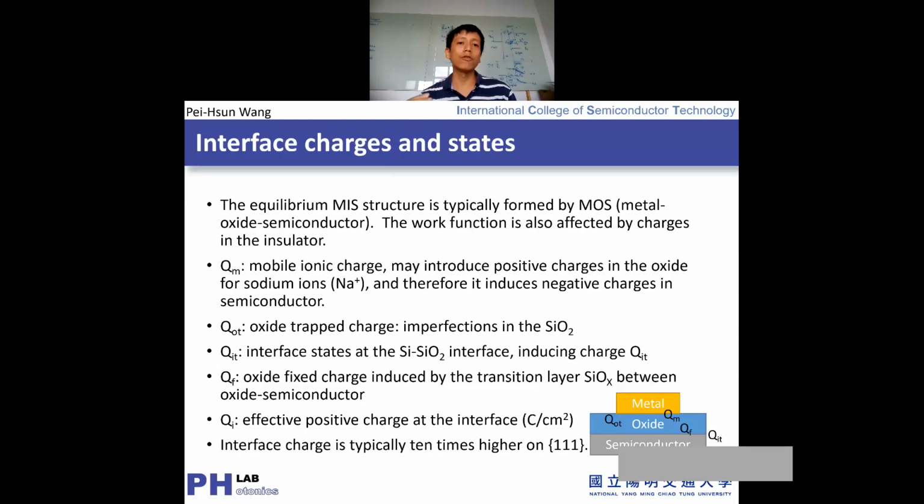Of course, you can also use different doping, but we seldom change the doping to meet different threshold voltage conditions, because in products like N3 or N5, typically we have 6 to 8 different threshold voltages, like ultra low voltage and standard voltage, in order to satisfy different devices.